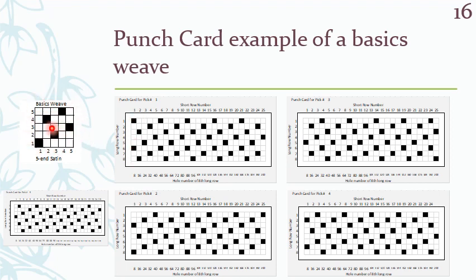If we have a bigger weave, for example here we can have 200 holes, so we can have up to 200 in one repeat size. As the jacquard is larger, the larger will be the maximum number of holes that can be inserted into a card. For example, generally a 1200 hook jacquard is available in mechanical jacquard format, or maybe bigger, and we need to follow not only the 5 warps but 1200 warps to fill these cards like this for the actual weaving process.